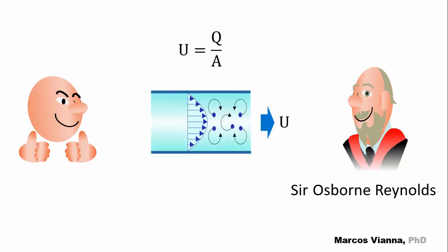We already know that average velocity is an important parameter. The greater the velocity, the greater the problem. And the diameter is also important. The greater the diameter, the greater the velocity differences will be. So, let's multiply both of them. Of course, viscosity is important. The greater the viscosity, the smaller the chance for eddies to take place inside the liquid. So, it will appear in our expression in the denominator.